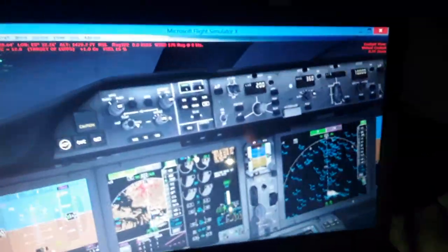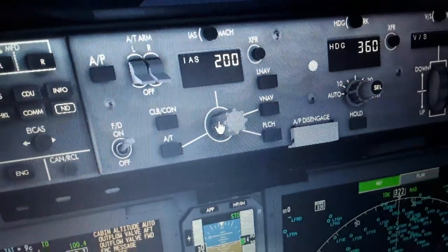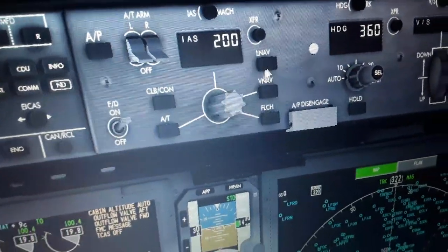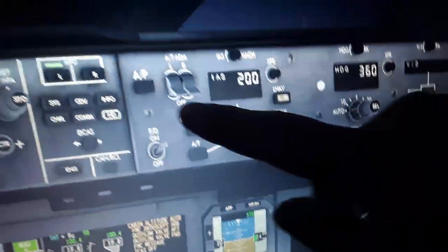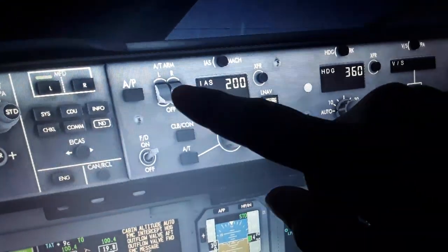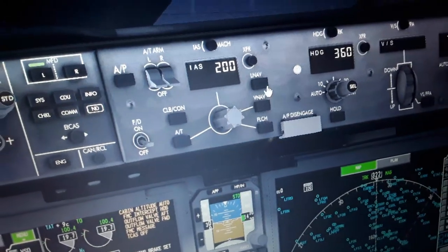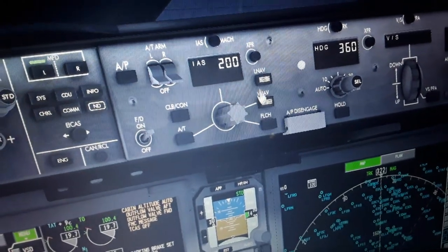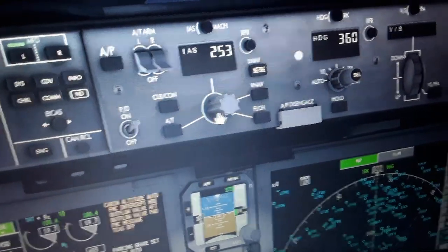Also now the autopilot flight director system panel, last thing before showing the overhead panel. So we set the autopilot flight director system panel. Here you see auto throttle left and right, arm and disarm, the airspeed select knob here, the LNAV and the VNAV if we arm LNAV and VNAV here. This is the airspeed guidance, the autopilot engage, disengage, the auto throttle left and right, the flight director. If we disarm the flight director, we cannot rearm the autopilot or any mode of the autopilot. We need to have the flight director armed all the time. So we change the airspeed like this, like 253.